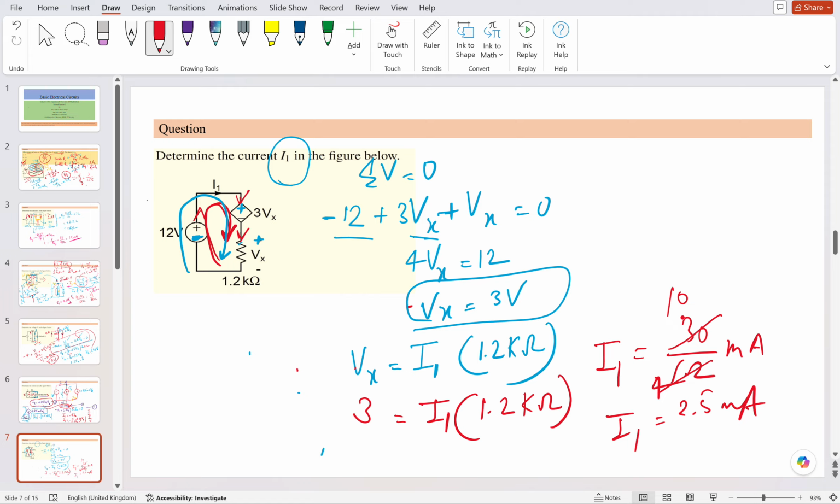Okay. So here the simple rule is KVL, but apply it through some method which you always take as a constant for your whole study. Don't change your rules, it will make things very easy. Always consider whatever potential comes first, and move forward in the loop and write the KVL equation. Any doubt in this?